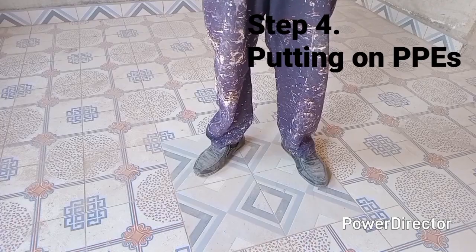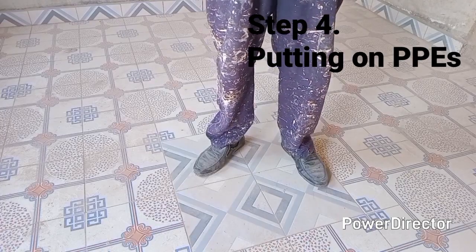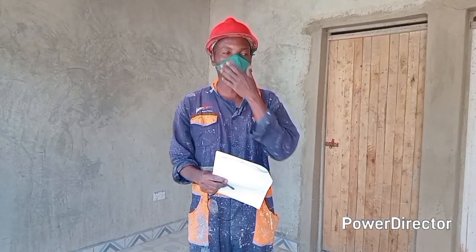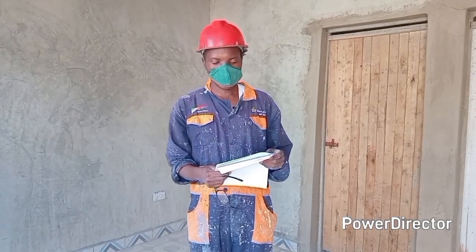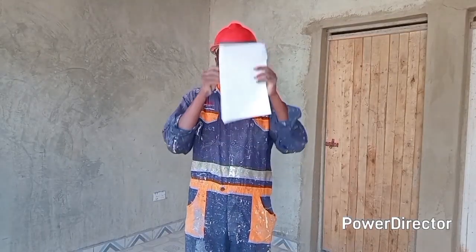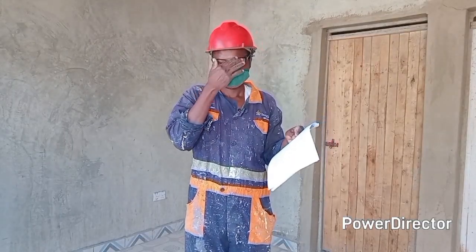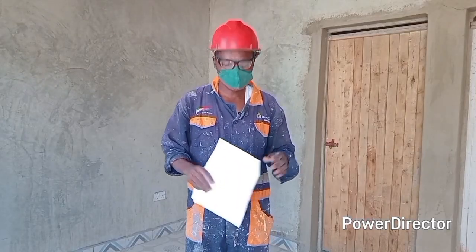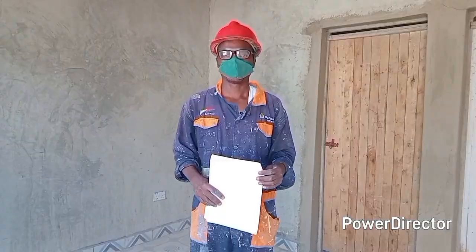Personal protective equipment, donning. We have safety boots, followed by nose mask, that is this one, here to protect me from inhaling the dust. And then we have the overall, the helmet, we have the goggles, that is this one. I must put this one to protect my eyes. So those were the PPEs that I must put on when I'm now doing the surface preparation.